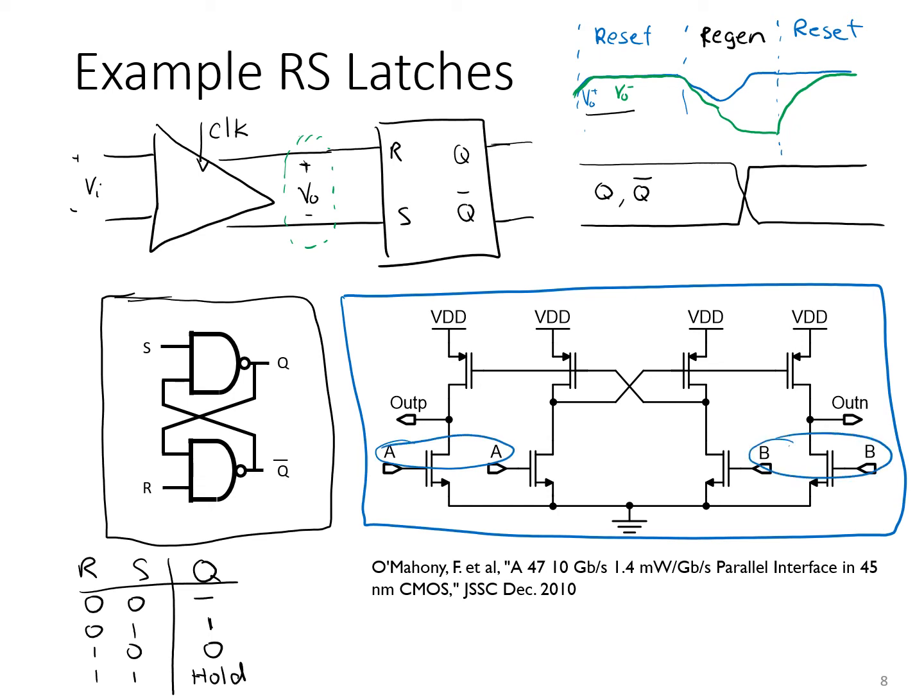And they're connected together. Let's consider first the example where A goes high and B goes low. In such a case, this node is pulled down to ground. That activates this transistor over here. That pulls this node up to VDD, logical 1. Doing so turns this transistor off. It also turns this transistor off. Remember that A is 1, so we get out P pulled down to ground.